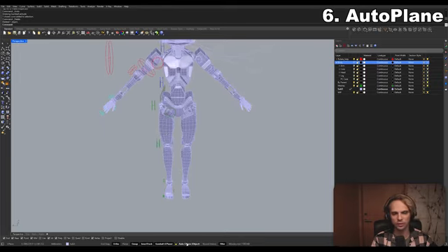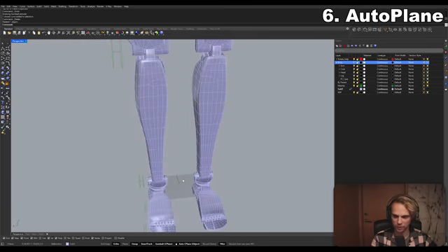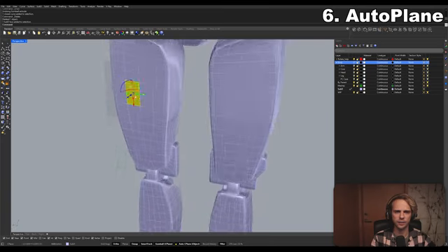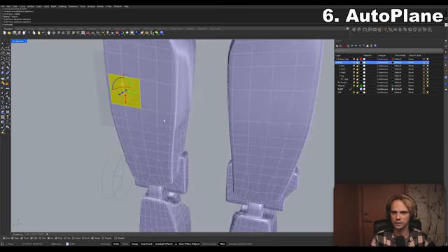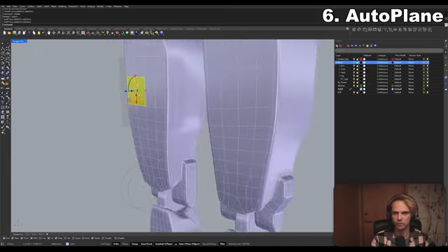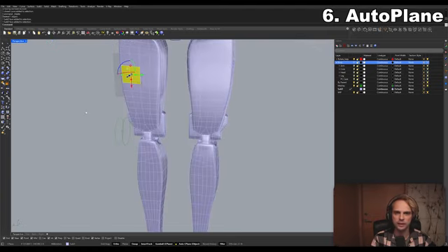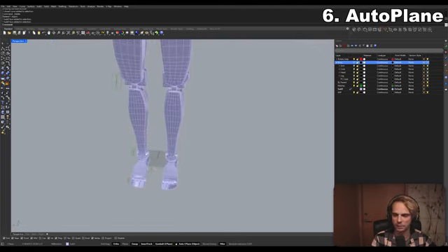So those are C-planes. Of course, if I right-click on this auto C-plane tool icon right here, I have the possibility to not have the C-planes sticky, meaning if this is unticked, then by default the C-plane is always world XY, well, at least in this perspective view. And then if I select this face, you can see that here the C-plane does change to fit on the surface selected or SubD patch selected. But then if I unselect, it disappears and it snaps right back to world XY. That is what not having sticky auto C-plane does, right?